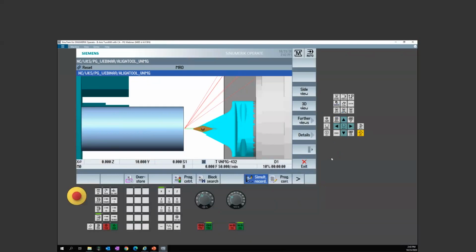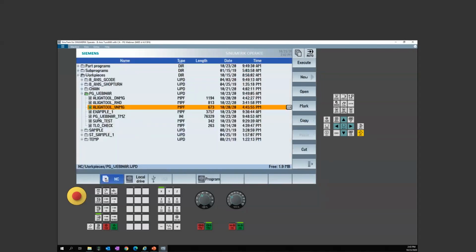But I want to show you the button tool, because there's two different ways to set up or configure the button tool. I can configure it working off the leading edge, or I can work off the center of the insert. That is always a question we get posed by the CAD/CAM guys: if they can't understand this tracking mechanism, how do they get the system to work off the center of the insert, and let them at least compensate for the radius.